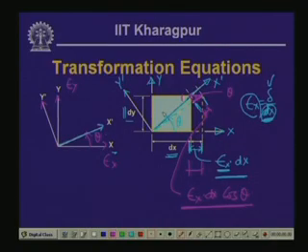Let us call that this particular diagonal is of length ds. So, originally it had a length of ds and it is undergoing an extension which is in terms of epsilon x, which is epsilon x dx cos theta, because of the extension in the x direction.